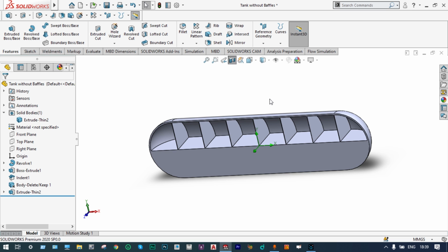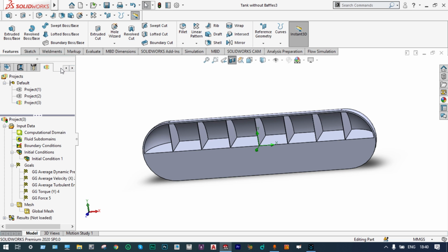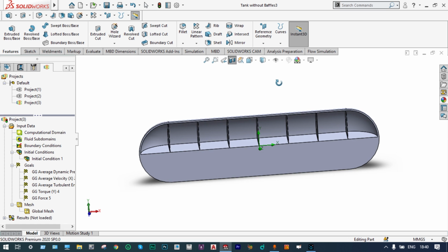Okay, done. So let us save these things with the name of tank with baffles. Save it. Next to that, we have to go for analysis. This is project number 3, and all things we have copied. That means we are not changing any parameter. We are not changing any input variable. All the things will be same. Now with the different design, we can run it.